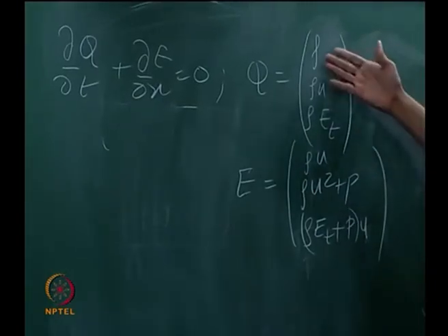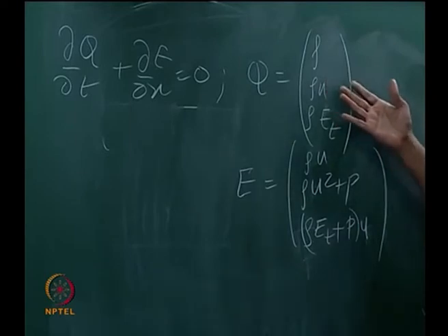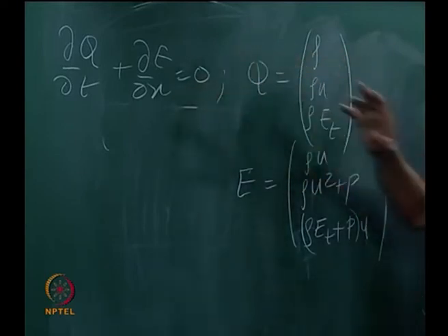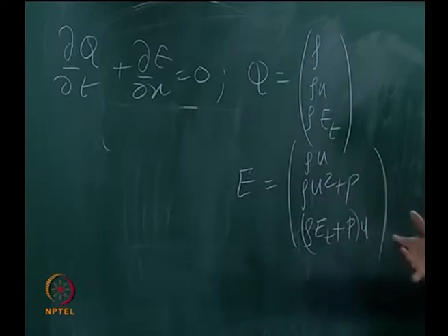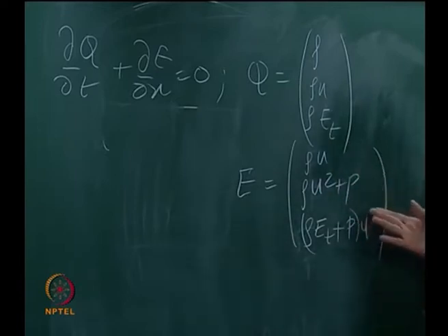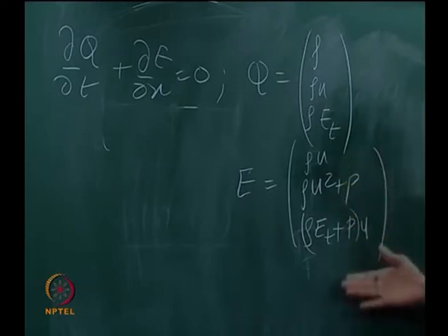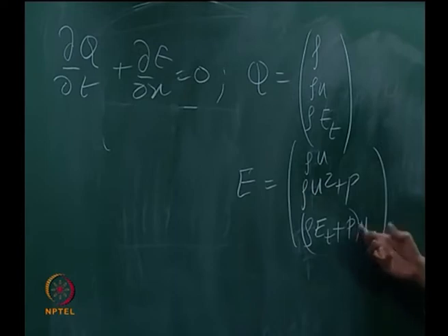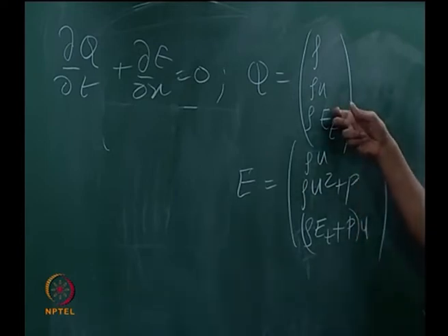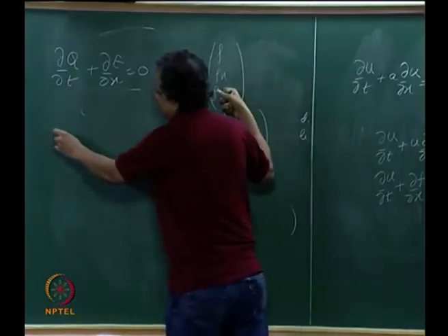These variables are said to be the conservative variables, it is written in a divergence free form, mathematically said to be written in a conservative form. For us of course from gas dynamics we know that across a shock these quantities are conserved, so you can give any reason you want as to why you want to call it the conservative form, but these are called conservative variables as a consequence, even if you write it in a non-conservative form.